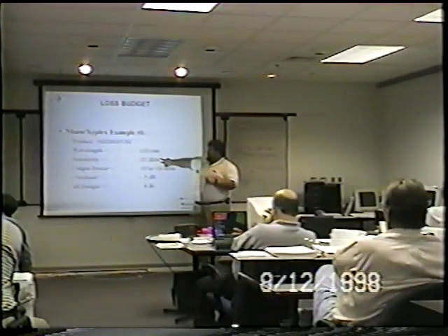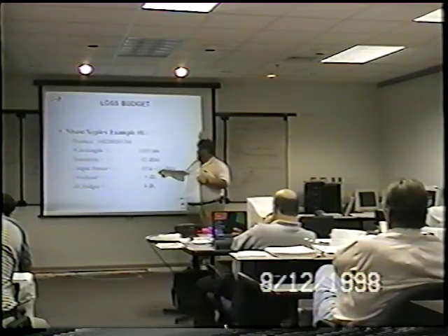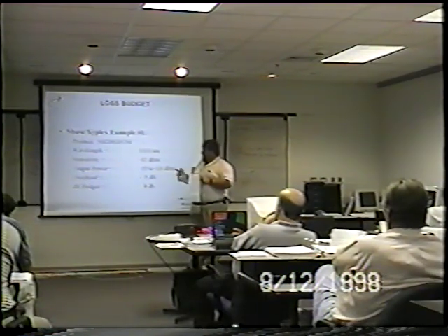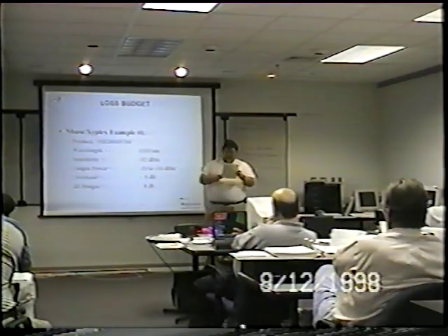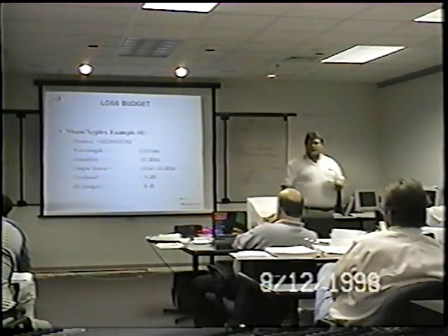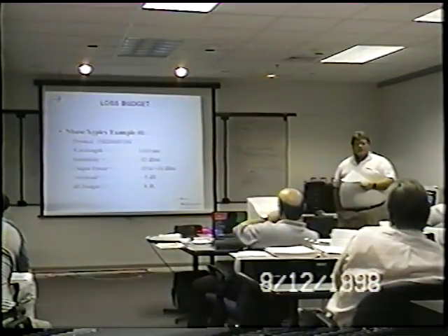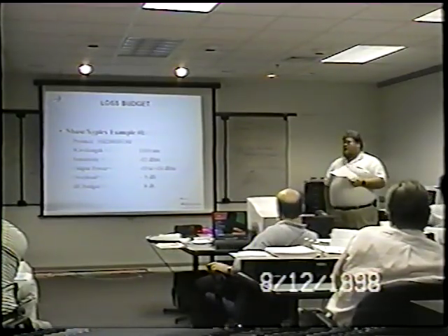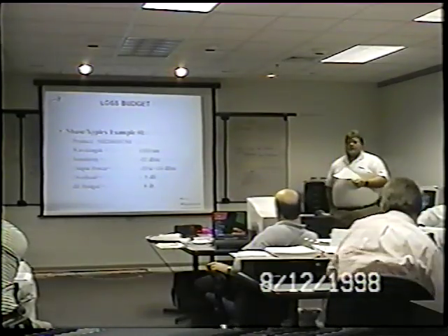1300 nanometers, my receiver sensitivity is minus 32. My output power is anywhere between minus 19 and minus 14. Another little figure here is called overhead. This is a pretty healthy amount of power that we sort of put in our back pocket here to allow for several factors. The average installation, the average number of connectors, patch panels, an average loss of fiber is all considered in that 5 dB.